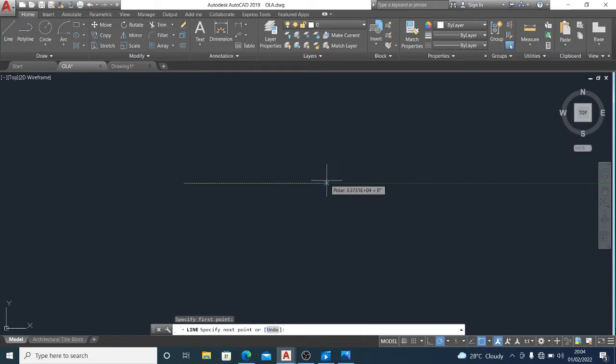You won't be able to navigate beyond the straight line. So how do I do that? You use your F8 command. By the time you press F8, it either activates or deactivates it. So I have my ortho command now activated.